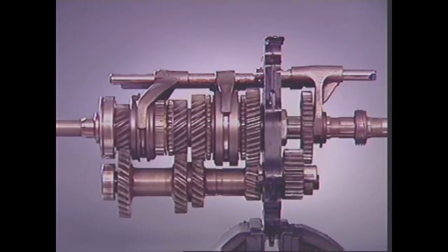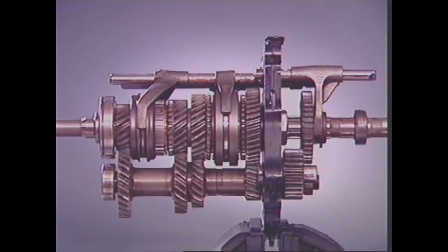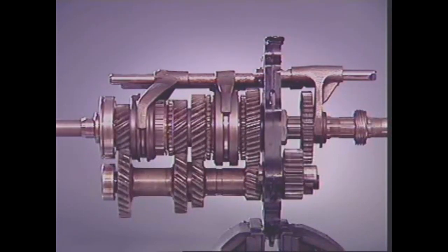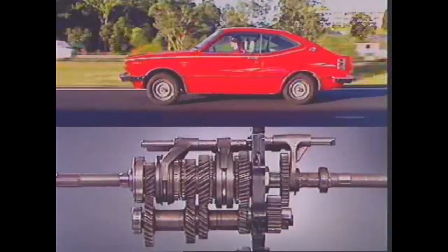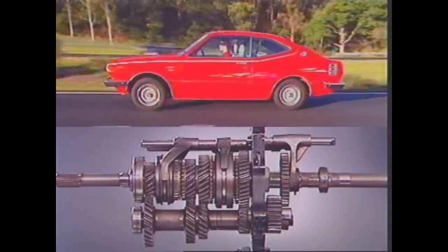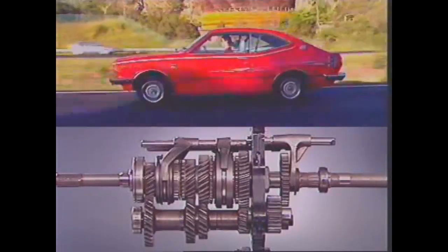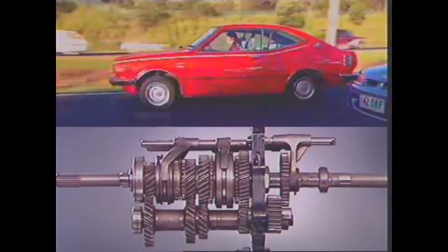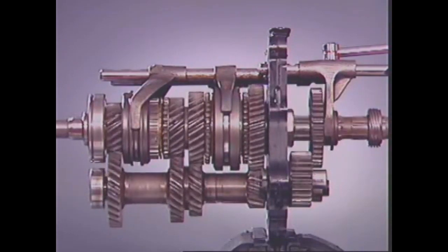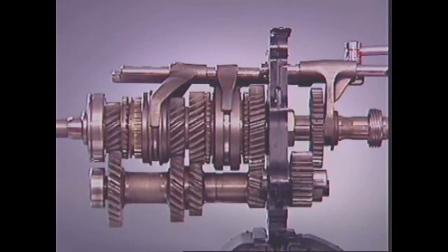The countershaft gears and their corresponding gears on the main shaft continue to rotate, as the countershaft is constantly in mesh with the input gear, but they do not transmit any drive. With the vehicle in motion, these gears will be turning at different speeds in relation to the main shaft and to the engagement sleeve, which is locked to the main shaft by the spline. When changing gear, their speeds must be synchronized so that the engagement sleeve can move smoothly into engagement.